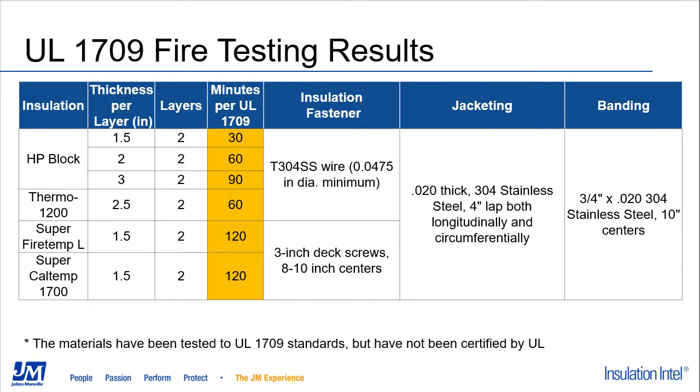Here is some of the information that is available on the performance that each of these products can provide. The performance is obviously very specific to the material being installed as per the configuration under which it was tested. So you do need to install the product in the thicknesses and layers that were tested, as well as the install method and the jacketing material and installation method as well.